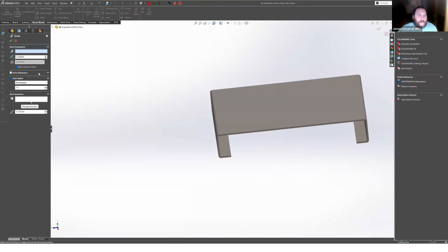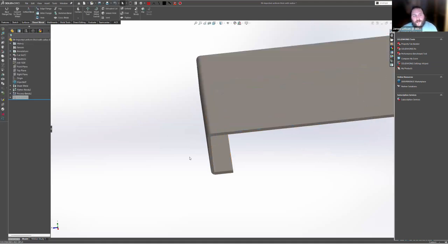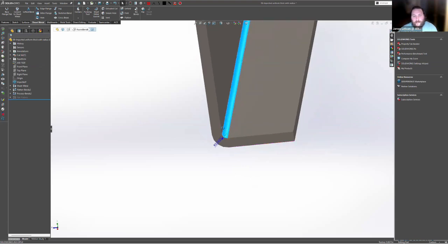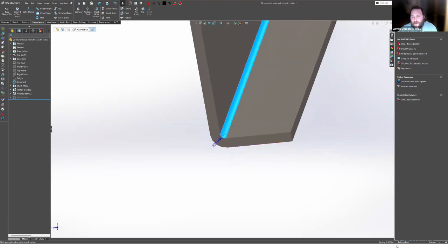So when we set bend radius, that's what it was. I set my bend radius to, let's set it to quarter or eighth inch, right? And I click this. The reason that we can't use insert bend is that it looks at what our bend radius already was on the solid part. And you can see when I click this bend down here on the bottom right, our radius is not an eighth of an inch. Like I said, it's actually a 16th of an inch.